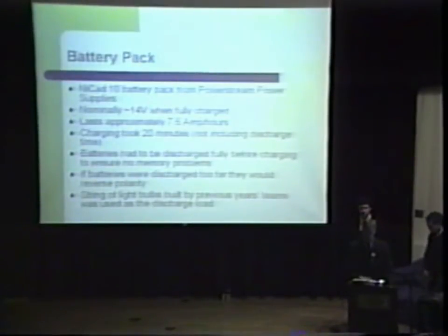And also, if we left the light bulb array, which we used to discharge it, if we left that on there for too long, it would actually change the polarity of the battery, which would pretty much render it useless. So I had to be kind of careful using that.